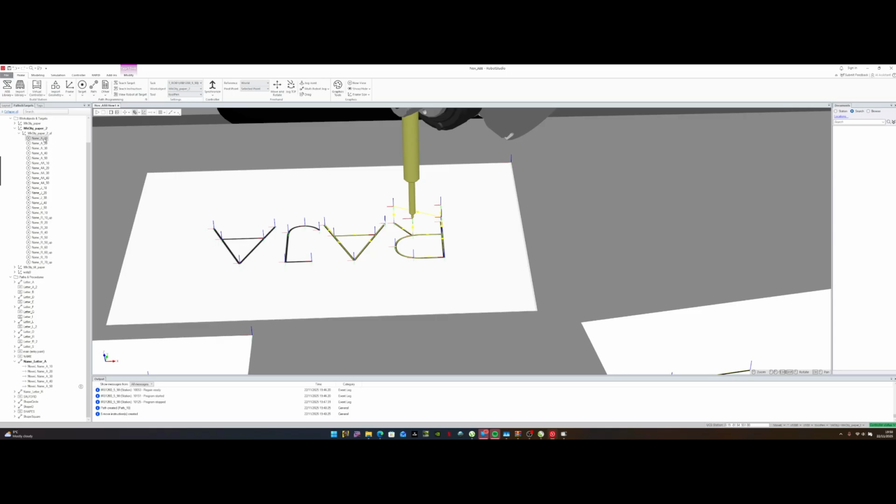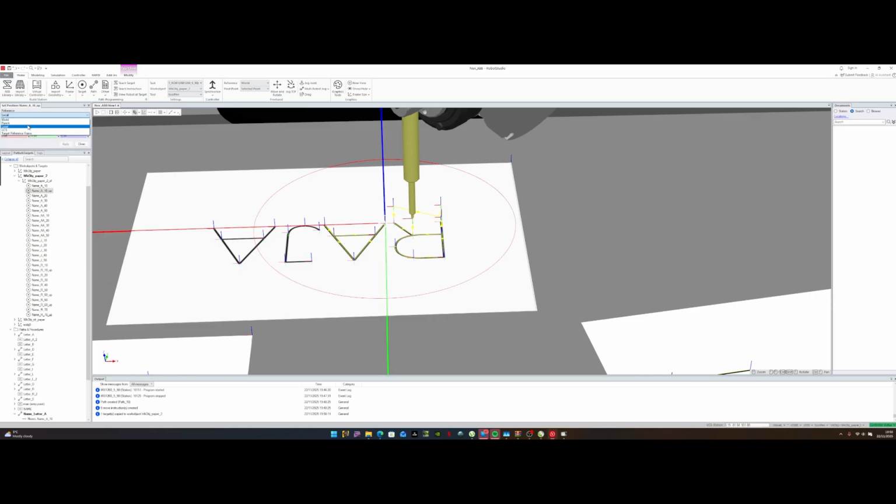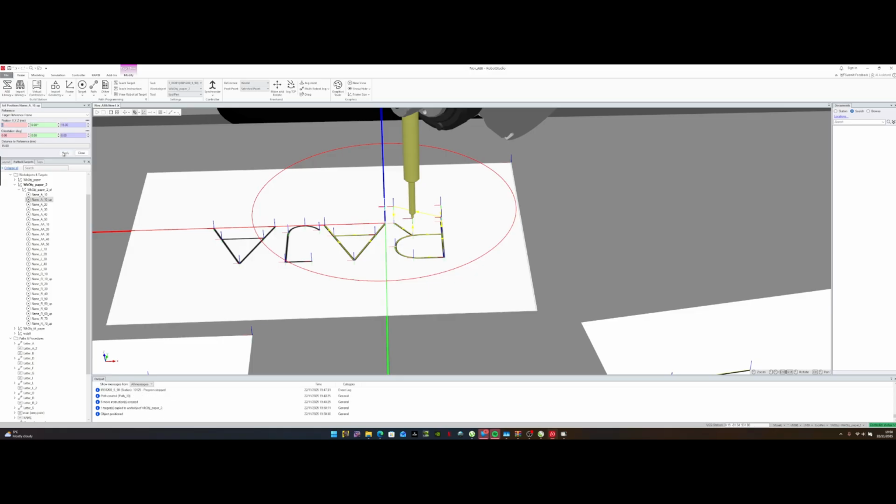This is the first target. I'll just duplicate this, Ctrl+C, Ctrl+V, come here, rename this to up, and then you right click on it, and then you go to modify target, set position, change it to the target reference frame, and then position, you set it to 15 again. I like 15. So that's up for that one.